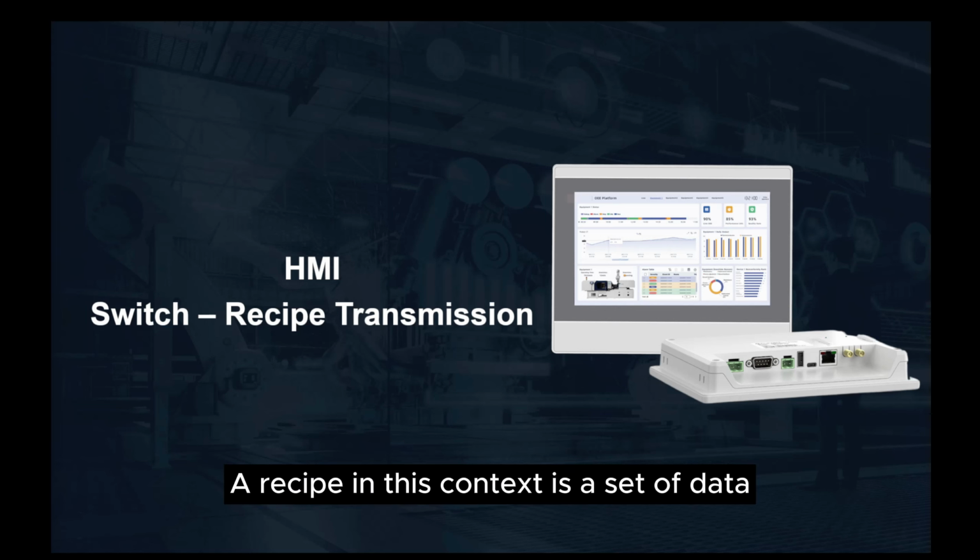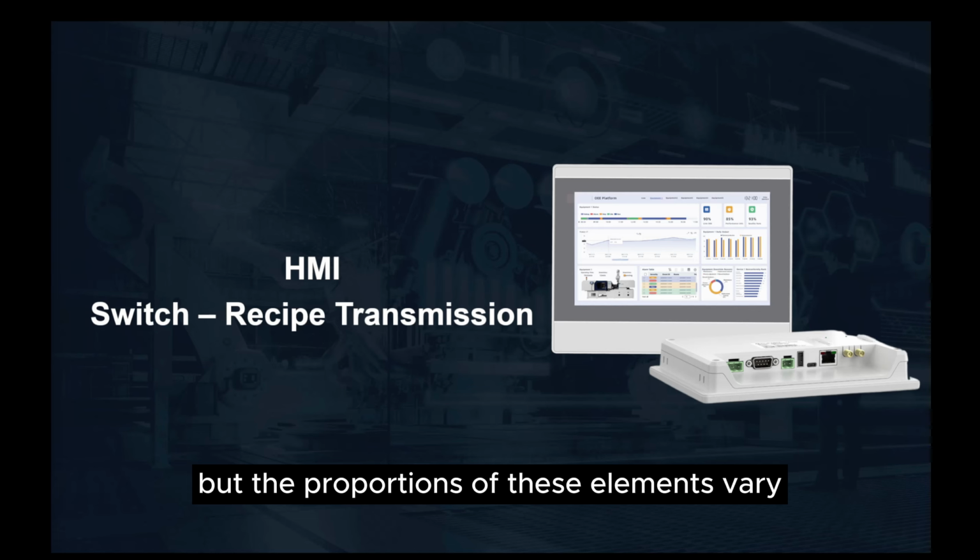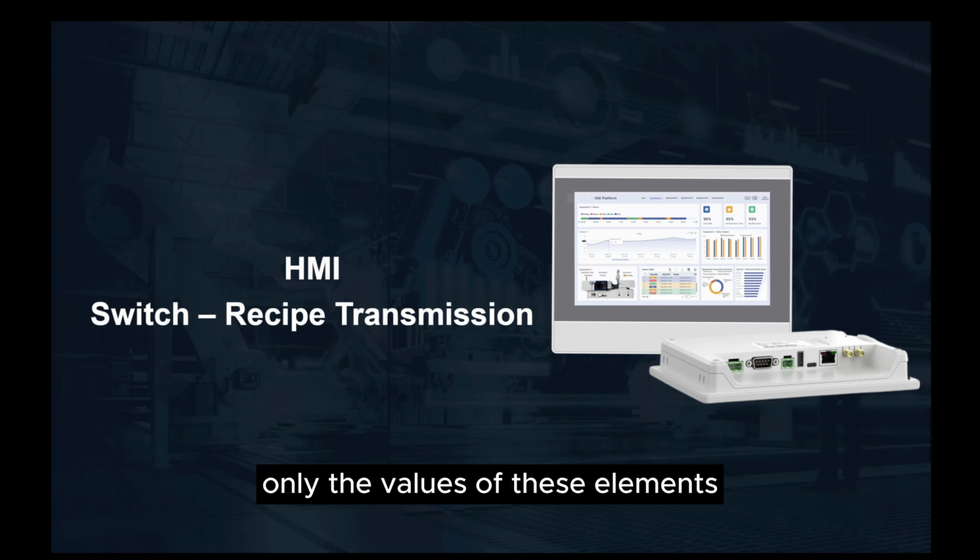A recipe, in this context, is a set of data. Imagine a production line that needs to produce multiple products. Each product has the same elements, but the proportions of these elements vary. When a different product needs to be made, only the values of these elements, the recipe data, must be altered.